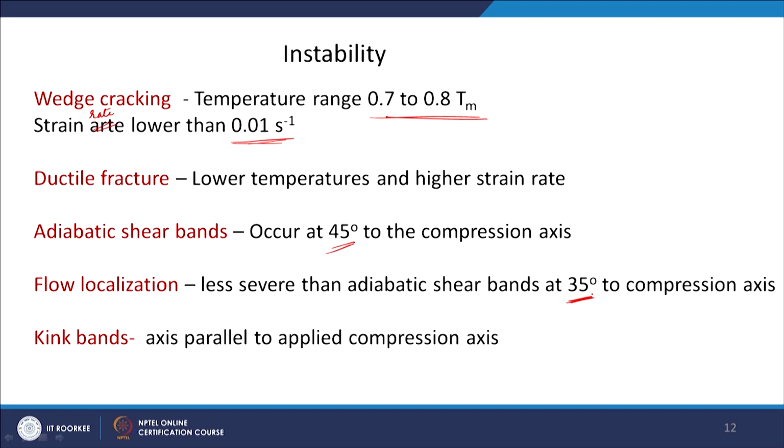If you know the pearlitic structure, where you have alternate bands of ferrite and cementite, when you deform this kind of structure, kinks develop in this lamellar structure.